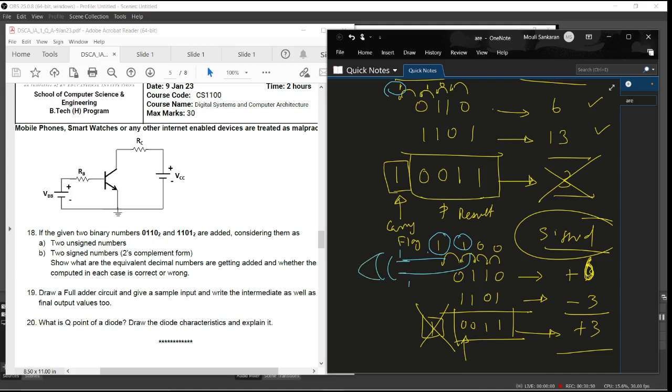In the hardware, there will be an XOR gate and it will set one flag, which is the output of an XOR taking the two carries coming out as inputs. If it is a 4-bit ALU, it will take these two carries. If it is 8-bit, it will take the last two carries coming out. So in this case, it's going to be 0. This indicates overflow in the case of signed arithmetic. If this flag is set to 0, it means that if this arithmetic is considered signed arithmetic, then there is no overflow.